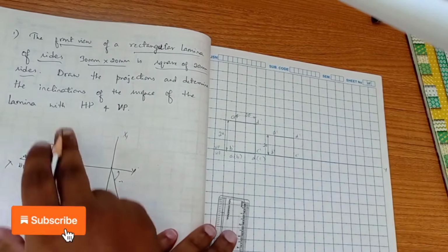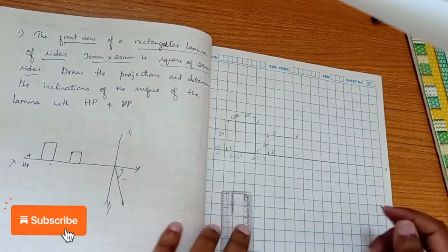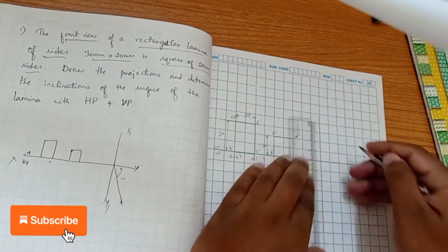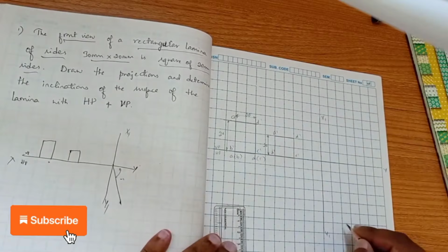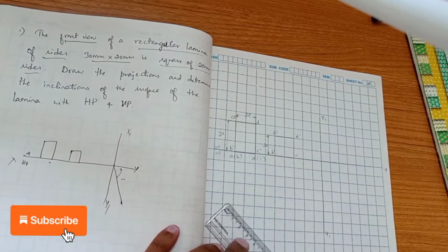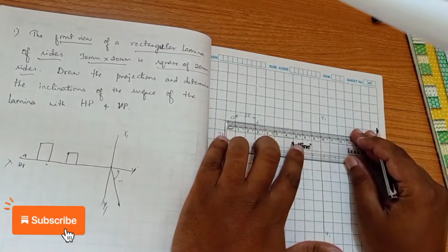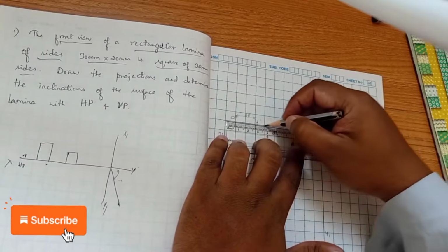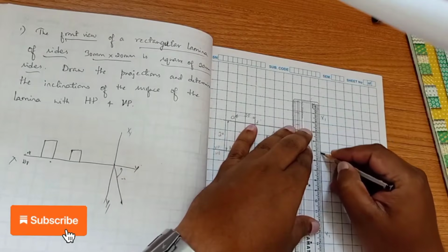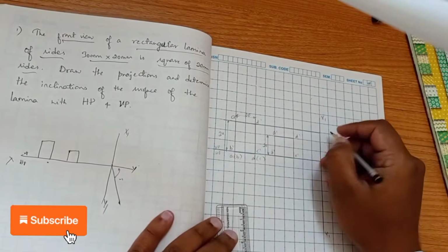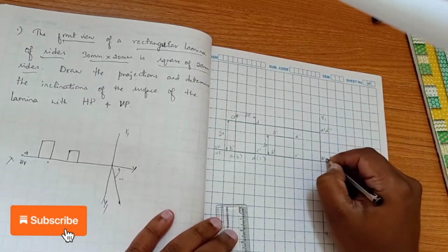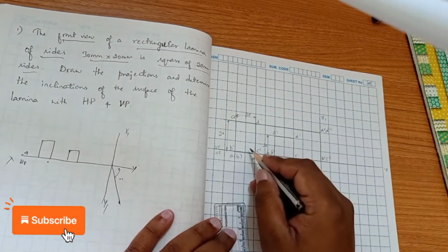So herein we have to find out the angle of inclinations. So how we find out here is we will be drawing an x1 y1 line, and we are going to project these side views. Like the side view of this lamina, the first position will be lying on this x1 y1 line. So what we get here is A double dash, D double dash, B double dash and C double dash. This is the side view of the first position.